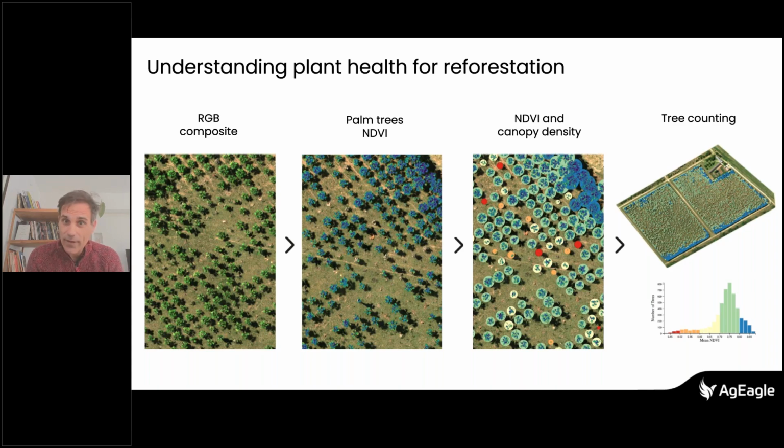you have that also on the camera itself, right? You can connect to the camera over Wi-Fi. There's a Wi-Fi dongle on the camera. So you can connect with your phone to the camera and look at the settings, do the pre-flight check, simulate your flight, and after the flight, you can also get into the configurations and have a look at it. You can also have some live view, especially interesting if you want to take a picture of your panel and see if you can shoot it right. Usually it is. If you just hold it above the panel, it's always right. All right. That's about the flight planning.